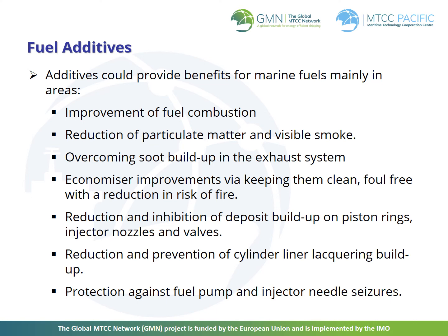Additives could provide benefits for marine fuels primarily in the following areas: the improvement of fuel combustion, the reduction of particulate matter and visible smoke, the overcoming of soot buildup in the exhaust system, economizing improvements through keeping them clean and foul-free, with a reduction in the risk of fire, the reduction and inhibition of deposit buildup on piston rings, injector nozzles and valves, the reduction and prevention of cylinder liner lacquering buildup, and protection against fuel pump and injector needle seizures.